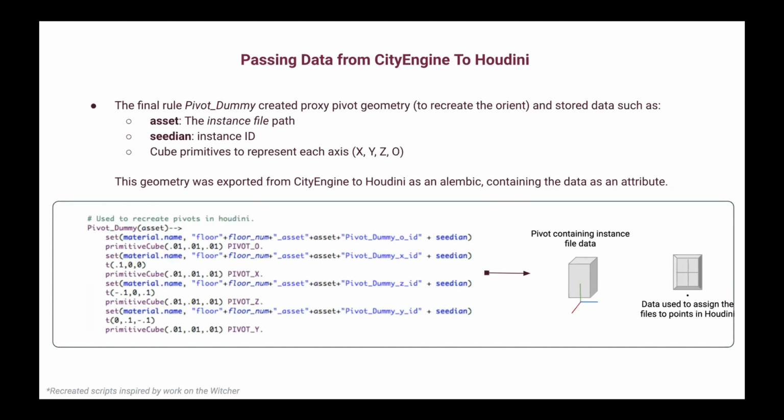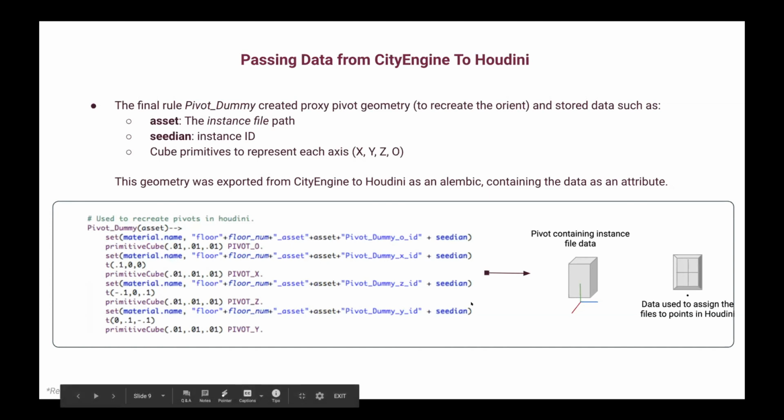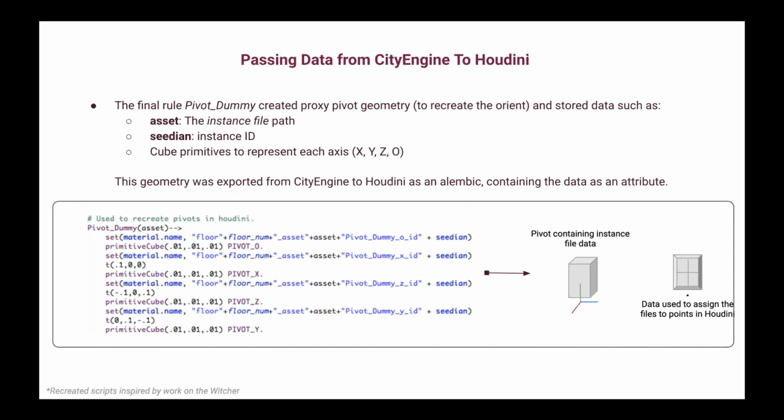So the modelers made roughly 8 variants of a lower styled window with several shutters which were either opened or closed to different amounts. So using the CGA value and some Python and VEX in Houdini, you could have more organic looking instances, because a building will never have all of its shutters closed. This will have a variety of some open and closed shutters.